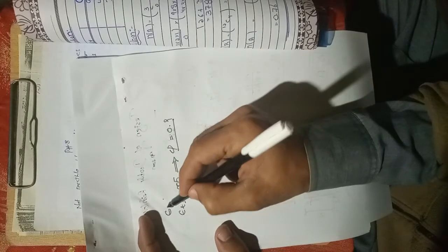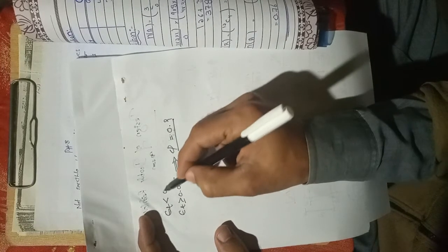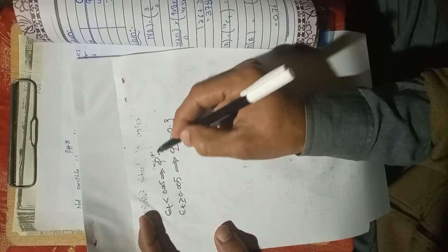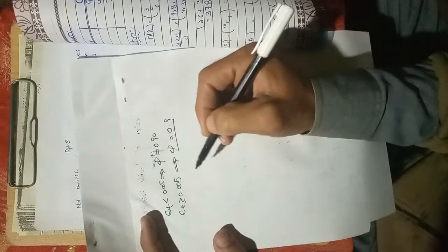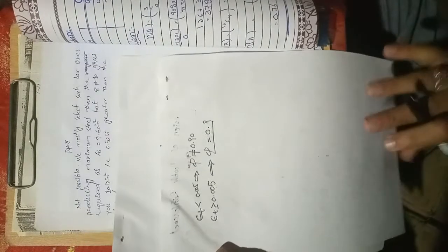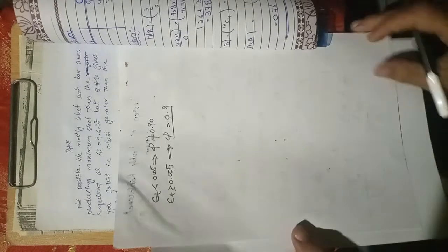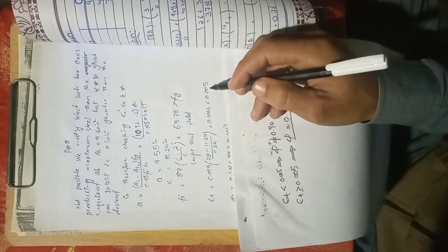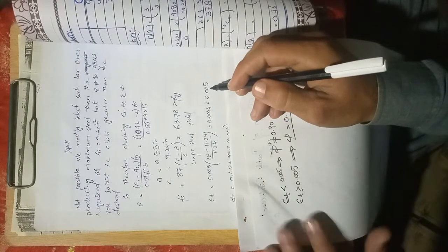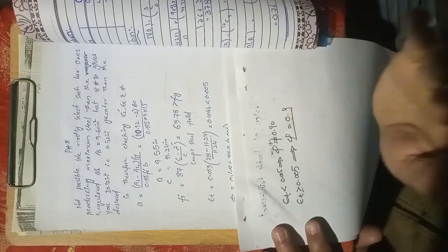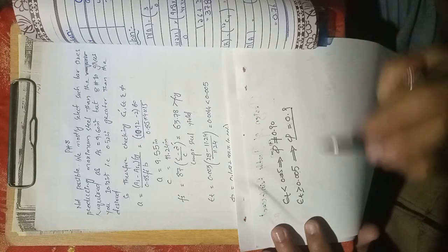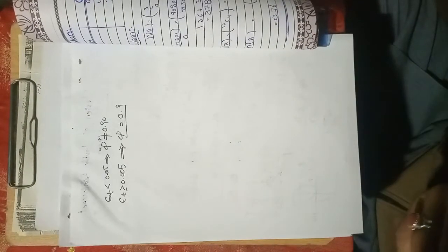If your epsilon t value is less than 0.005, this means that the phi value is not equal to 0.90. So let's see, we calculate the epsilon t value, and the epsilon t value is 0.0044, which is less than 0.005. That means the ductility check is not okay. This means the phi value of 0.9 is wrong, right? We have to calculate the exact value of phi.